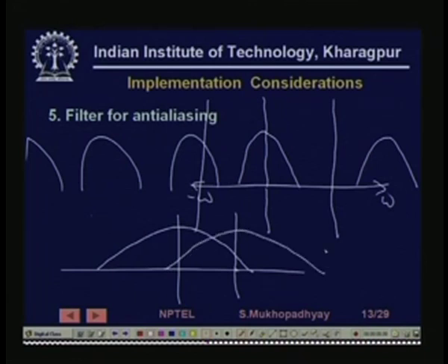So, what will happen is that effectively once these two lobes, if you take summation, then you are going to get a frequency spectrum of the digital signal that will look something like this. So, you see that, but this is a very important part of the signal, generally for control the low frequency part is very important. So, you see that the high frequency part of the signal, which was not so important for control, has kind of folded back and it has come onto the low frequency part and is now affecting the low frequency part, which is important.